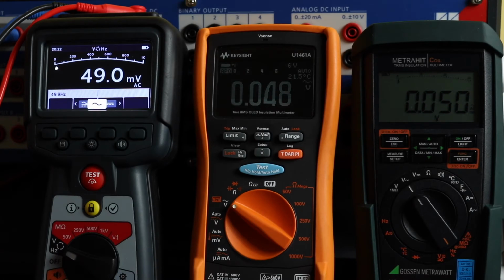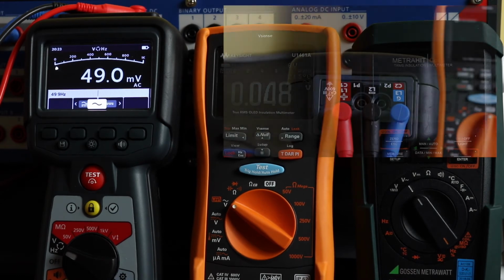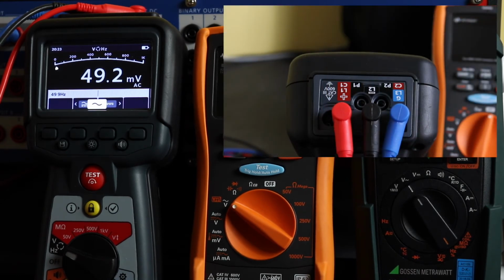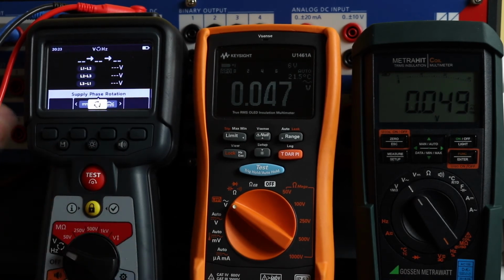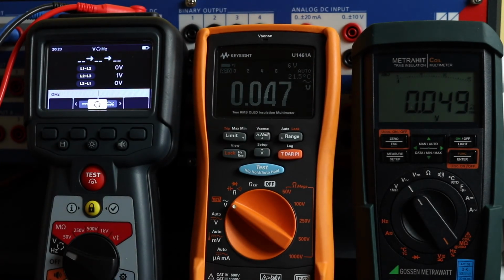While you've been perusing the plots and tables of the voltage accuracy measurements, I've reconfigured the test set for a three-phase voltage measurement that the MTR105 can do, which the other two instruments cannot do, only by swapping over the leads. For the MTR105, all three leads are connected up, and to get to the three-phase measurement, it's just off this menu here, and there it is in front of you.